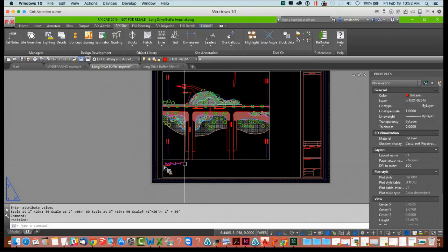Great. Okay, so you guys have another 5 minutes or so to get in any last questions that you might want to cover. So basically, I wanted to finish this off with a quick mention of this other scale option within AutoCAD, other than the Land F/X plot scale. There is annotative scale. Now, while annotative scale can be very helpful in very specific situations, I'm going to go ahead and say that nearly all of you shouldn't bother with it. I'm only going to go into it enough for you to recognize when a plan is set to use annotative scaling so that you can remove it.